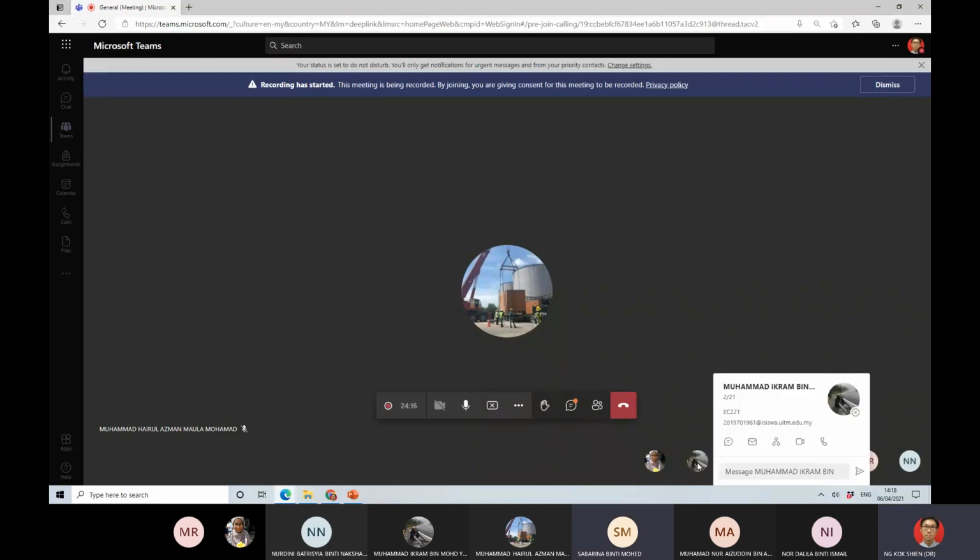Elastic modulus. Okay, elastic modulus will give you a Young modulus. So Young modulus normally refers to elastic modulus. Other than this Young modulus, what other kind of modulus you have? Secant modulus. Okay, we can have a secant modulus. A secant modulus is still the Young modulus, but the slope that we calculate is from a different point. It's still considered Young modulus. Like secant modulus, tangent modulus, initial modulus, they are all considered as Young modulus.